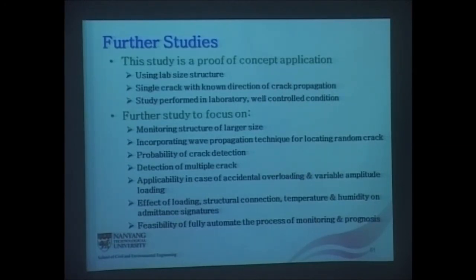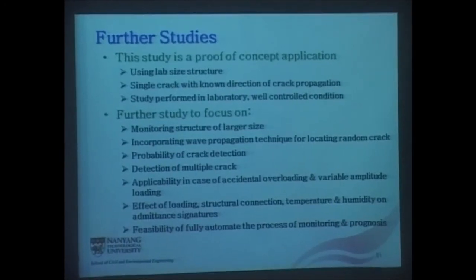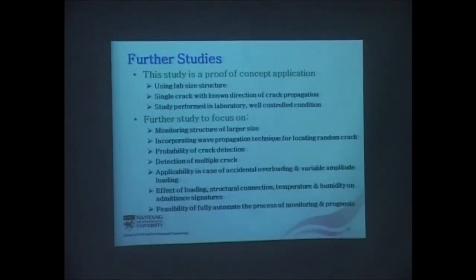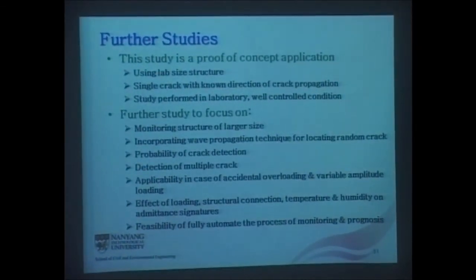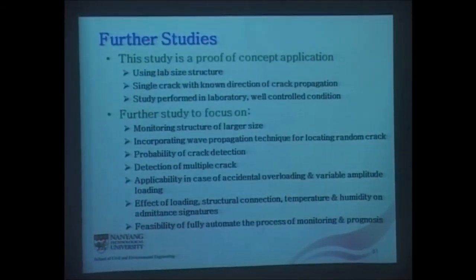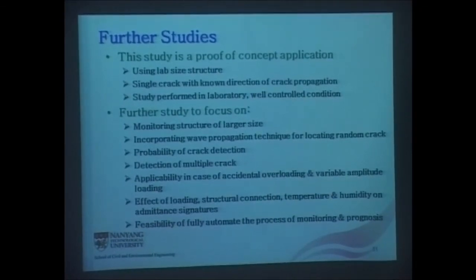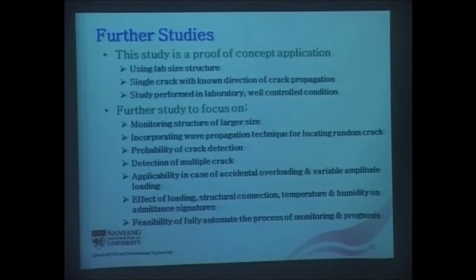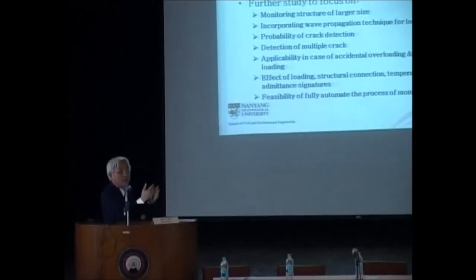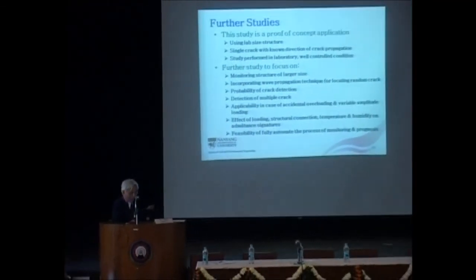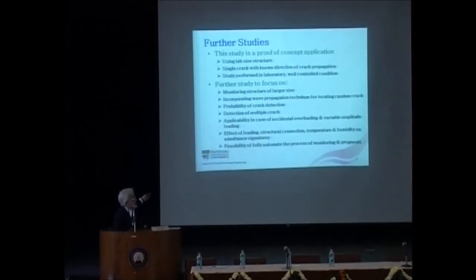Right? SN curve, you have so many SN curves, and to do an SN curve, you have to do at least 4 specimens. And a specimen can be expensive depending on what type of joint. I was from offshore. So a big part of my work was to produce SN curves for tubular K joints and T joints. Those of you familiar with offshore structures, K and KT joints are very complex. To do that is not that straightforward. So this is just one test.